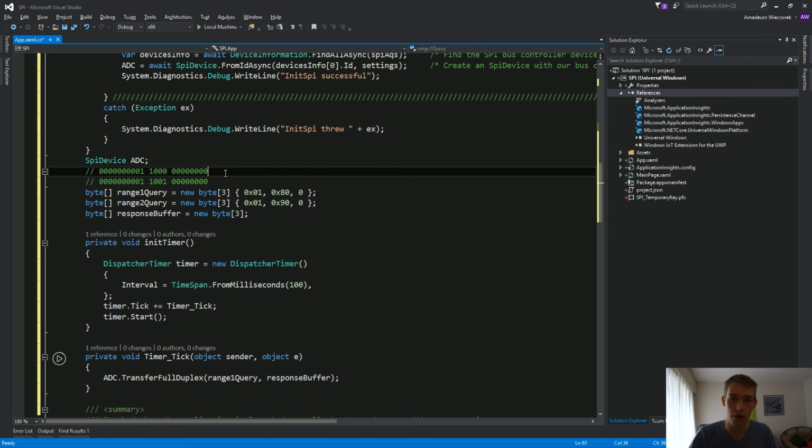So this will probe the first sensor, this will probe the second sensor. Now let's convert it to hexadecimal format. To make things easier, I set the byte boundaries here where our information actually changes. In the first byte, we're just sending 1 to initialize the connection. Then in the second byte, we are sending the data that we need to send. And then in the third byte, we're just sending zeros.